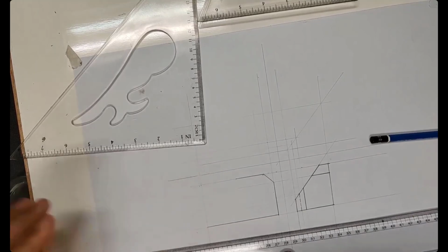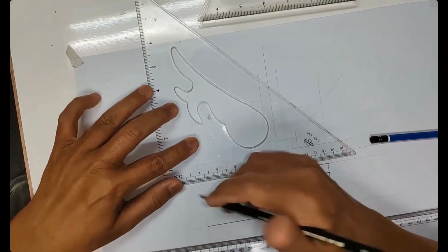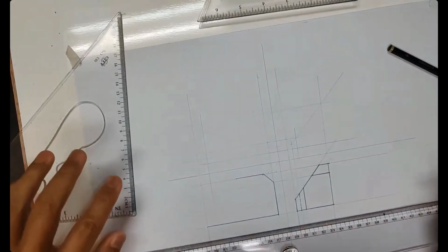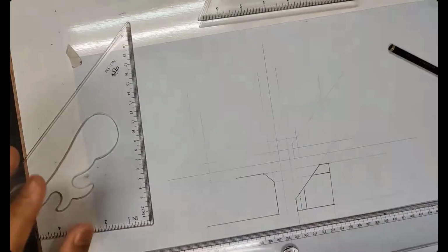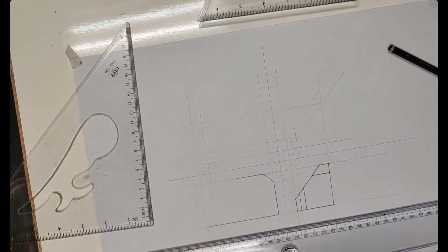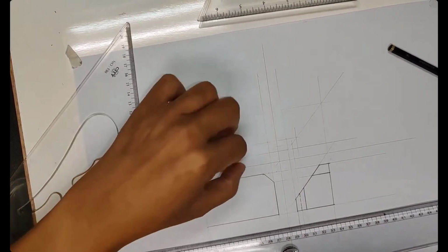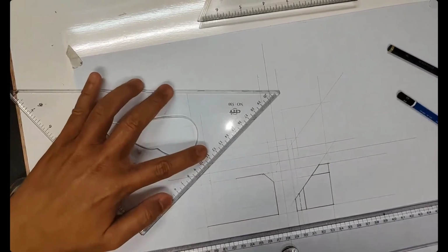On the front view, we have a chamfer with a distance of 10 units on the right. So I have a 10 unit from here and 10 unit from here. Do your extension line for H, bring it up. Guys, my drawing is not accurate, frankly, because I'm not in the right position. I cannot see perpendicular to the paper, so there is a little bit of misalignment. So I have a 10 there. Here on the front view, I have a chamfer that clearly shows the chamfer. The chamfer will stop here.